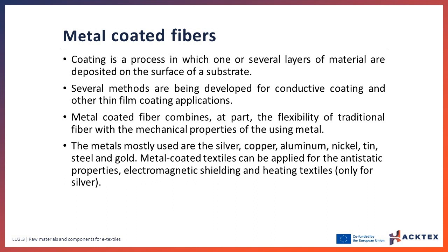These include electro-less plating, where surface layers of metals are formed on the substrate via chemical reactions in a coating bath; sputter coating, where a thin layer of metal is formed by incident particles or ions accelerated by an applied electrical potential colliding with the surface; PVD, physical vapor deposition, where vaporized material is transferred to the substrate surface and deposits a thin film on it; and CVD, chemical vapor deposition, in which the surface is modified by depositing layers through chemical reactions in a gaseous medium.